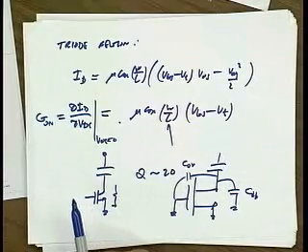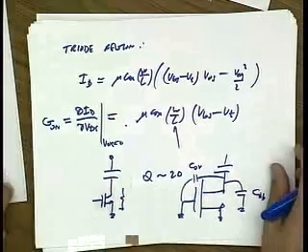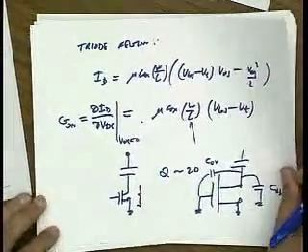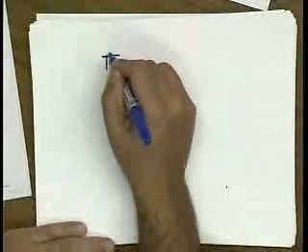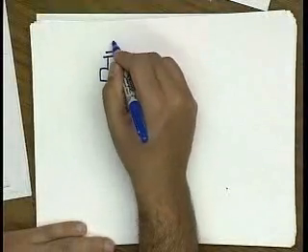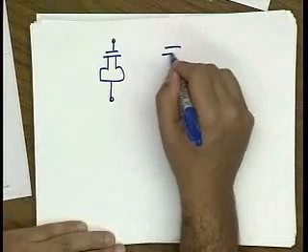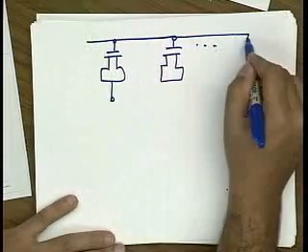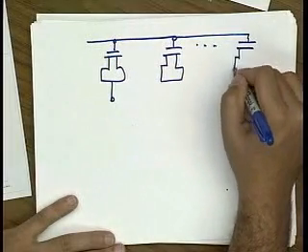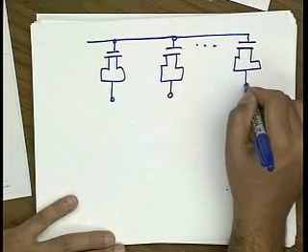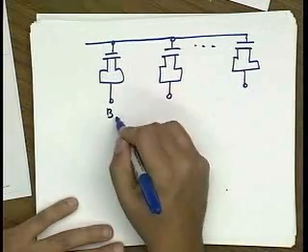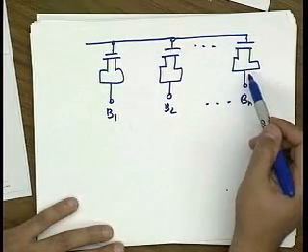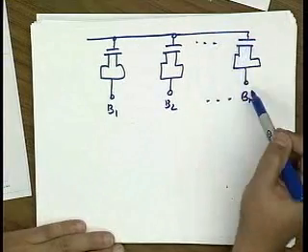Okay? Now, Al showed you guys another idea, which is clever. Instead of using a switch capacitor, just use a MOS device and use the body voltage to switch its capacitance. So I could have a binary array of MOS devices, and I use this body voltage basically to either switch this into accumulation or into deep depletion, and that would change its capacitance.